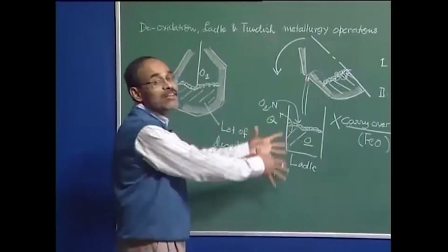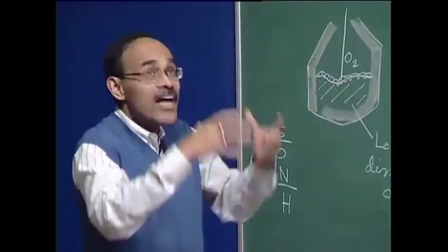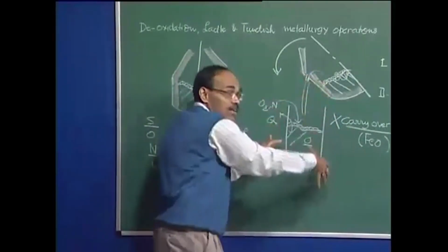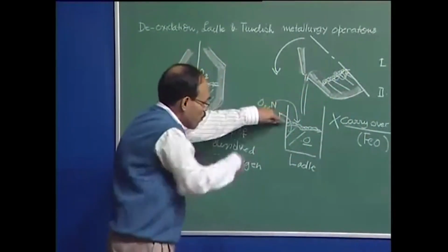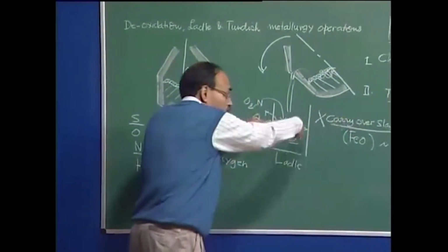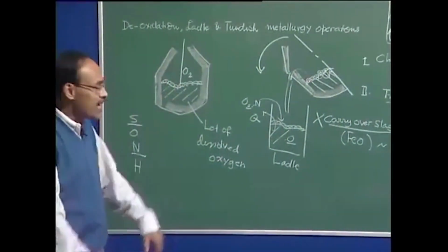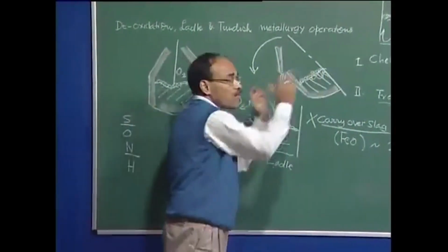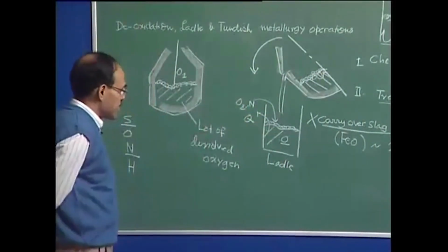And finally, the ladle will be placed over the turret in the continuous casting mill, where it is going to be cast. And as the ladle over the continuous casting mold is emptied, it is going to be recycled back and brought under the primary steel making furnace, and this is called the recycling of the ladle. From here it goes to the continuous casting bay, and from the continuous casting bay an empty ladle comes, and so a ladle is going to be used for a number of hits before relining is necessary. But typically we must understand that the capacity of the ladle and capacity of the furnace are going to be identical. One hit is going to be poured in one single ladle itself.